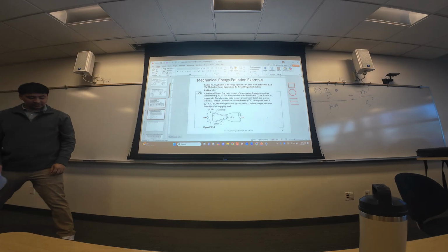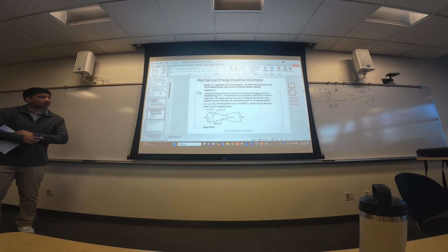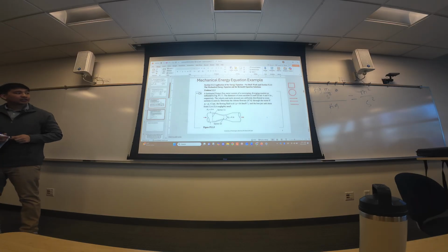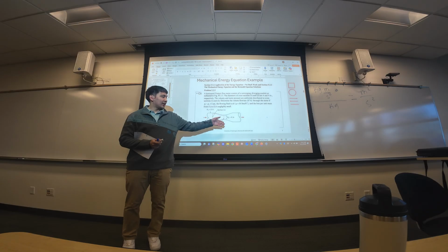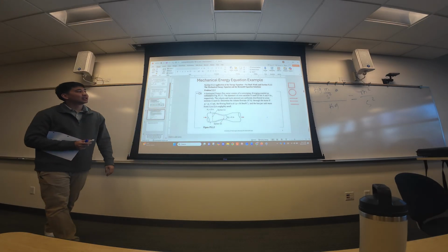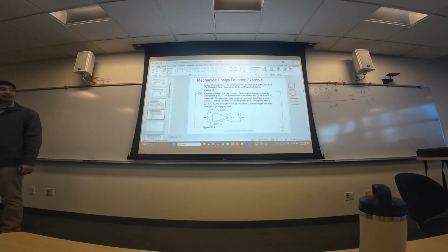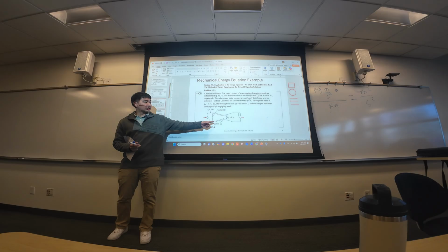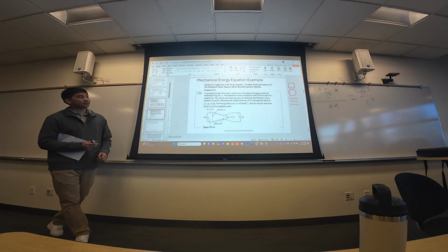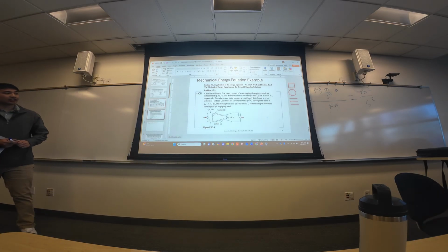Okay, so let's read this. A horizontal Venturi flow meter, which is essentially just this tube that has a narrow passageway here, consists of converging, diverging conduits as indicated in that figure. So the diameter of the cross section, there's cross section 1 here and cross section 2. And you see that there, right? D1 is 6 inches, D2 is 4 inches.